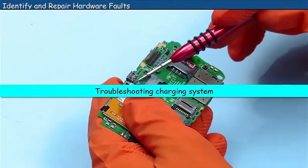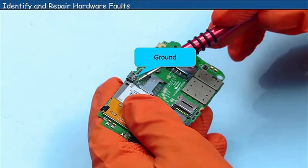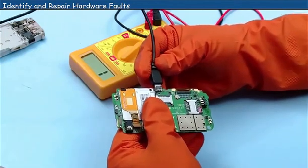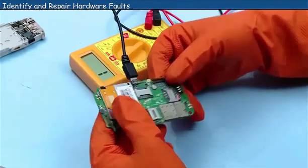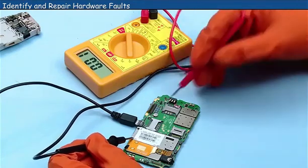Troubleshooting charging system. Locate the charging point and clean it using a blower. Check the charging point for physical damage. The charging point has 5 pins, namely positive, ground, and 3 signal pins. If there is no problem in the charging point, then check the supply from the charging point to the battery pin. To check the continuity, use a multimeter.